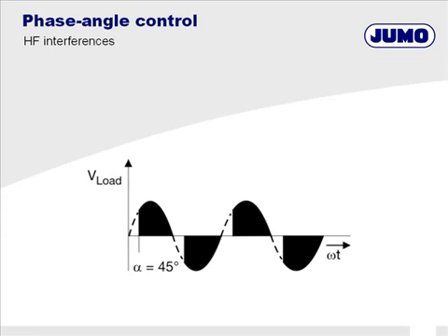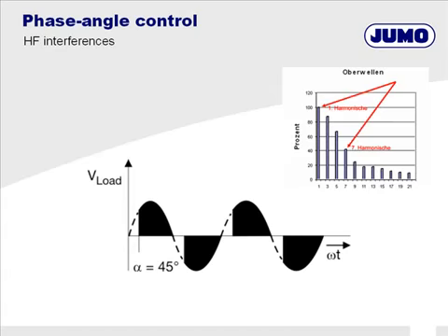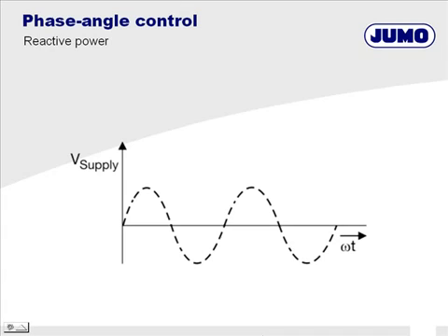The Thyristors are not switched in the zero crossing point. Because of this fact, there is a big EMC error potential. The Thyristor unit in phase angle control generates reactive power in the event of a control angle bigger than 0 degrees. The example shows the supply voltage.